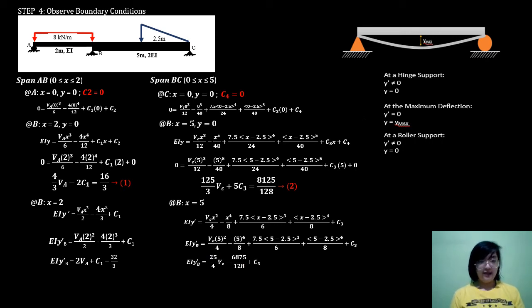Let's draw the elastic curve because this is more complicated than the other boundary conditions. I'll show you. Here, we can say that our elastic curve looks like this. So, this is our beam. We can see that the slope here in segment AB and the slope in the other segment, BC, are the same.